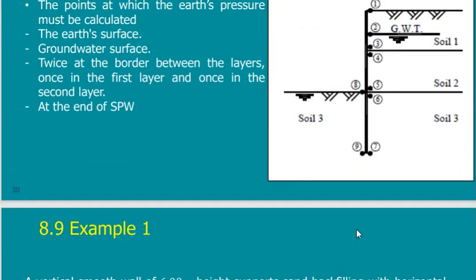Usually, if you are calculating below soil and you have something here and something there, it is better to have values on both sides. If you need a value here, then you need to know the value on the other side. This is for the ease of calculation, not a must. Here I did not calculate anything because I know that the pressure on the other side, the active side, what is the passive pressure at 1, at 2 and at 3? Zeros. So I don't need to calculate them, I know them.